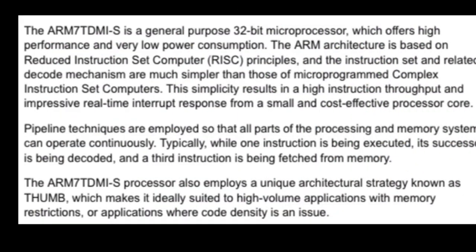Before I begin with the lab session, let me revise the ARM7 TDMI and the LPC2148 features. Firstly, the ARM7 TDMI is a general purpose 32-bit microprocessor. ARM7 TDMI is nothing but an ARM7 with a 16-bit Thumb instruction set plus a JTAG debugger plus a fast multiplier with an enhanced ICE. It implements the ARM version 4 instruction set. It offers high performance and very low power consumption.